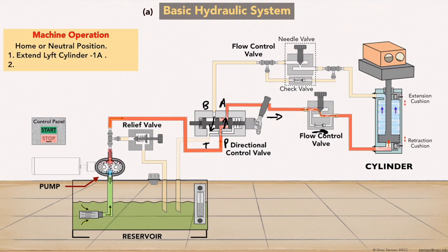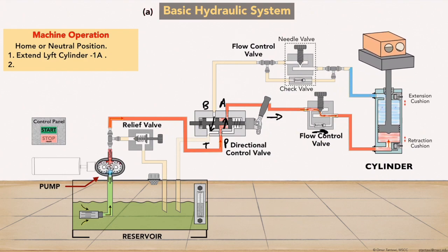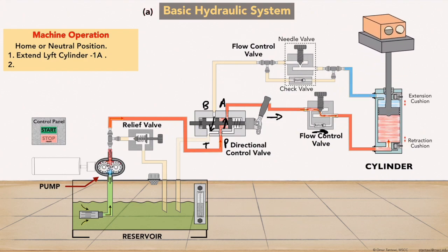This flow must build high enough pressure on the piston to push the load up. But to be honest, this happens instantly since the oil is a liquid and liquids are incompressible. But since this is an animation and for explanation purposes only, there's some delay time. Pressure is just an exertion of a continuous force upon a surface. This force is directly related to the piston surface area. The larger the piston, the more force can be exerted.